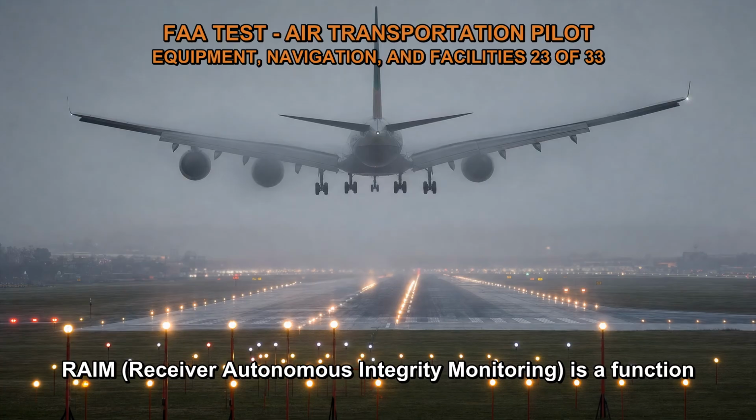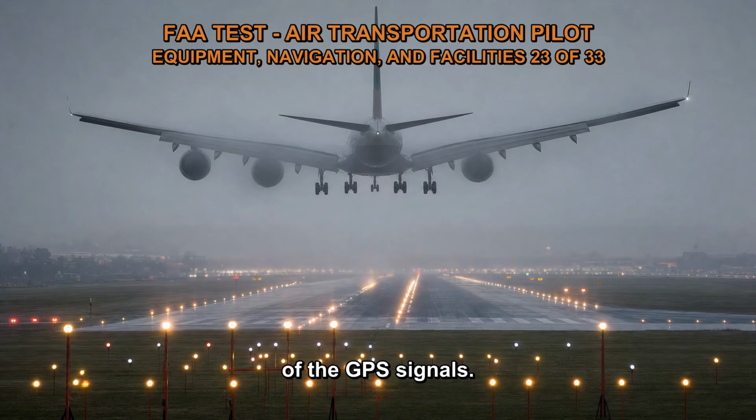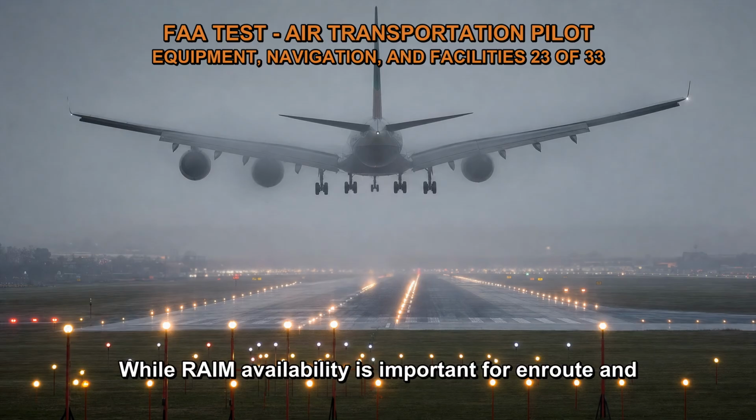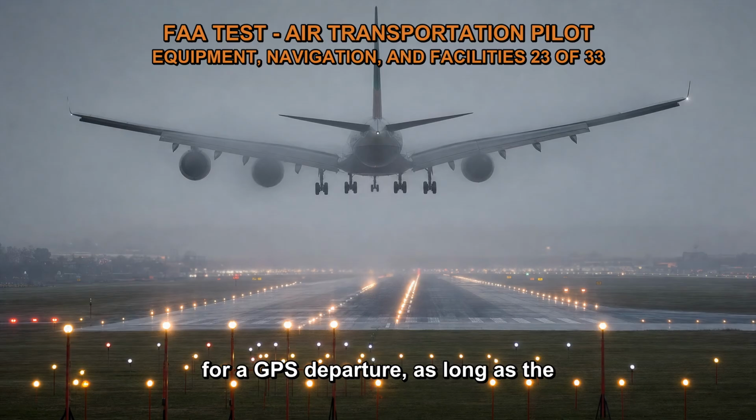RAIM, Receiver Autonomous Integrity Monitoring, is a function of the GPS receiver that ensures the integrity of the GPS signals. While RAIM availability is important for en route and approach operations, it may not be specifically required for a GPS departure, as long as the waypoints are part of the active flight plan.